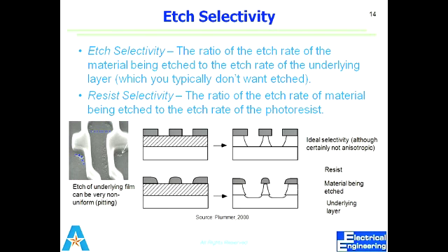In most processes, when you need to remove a certain film absolutely, you always go for an over-etching process. If I know the thickness of the film and this is my etch rate, then based upon those two things, you calculate the time to remove all that film thickness. I will always go for over etching, maybe 30 seconds extra, maybe 1 minute extra, depending on the etch rate, so that there is no residual of the film left there.